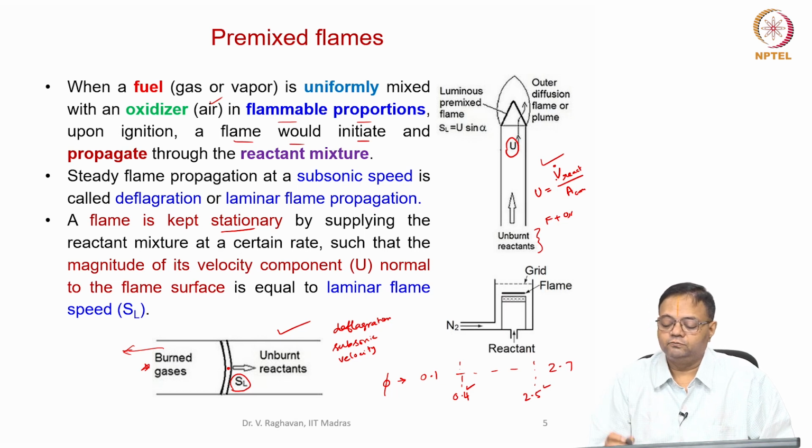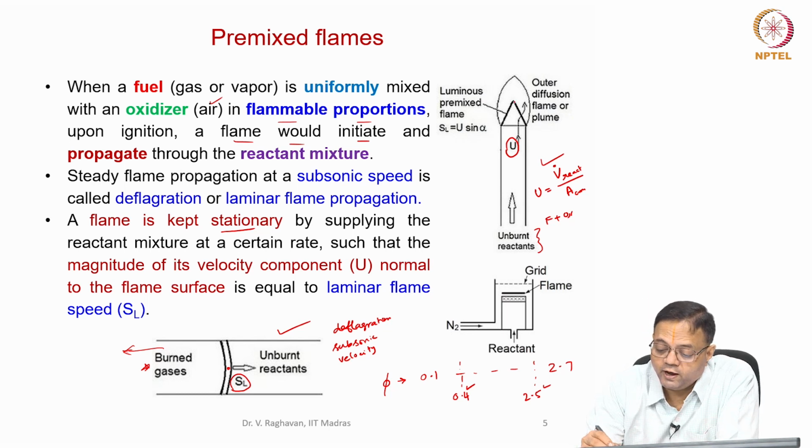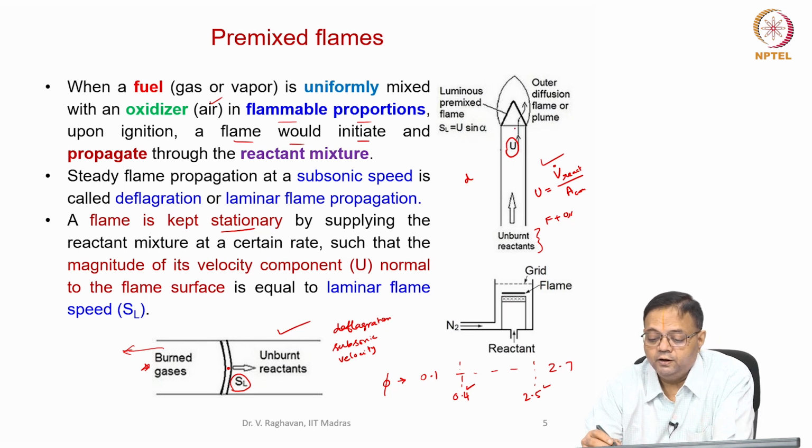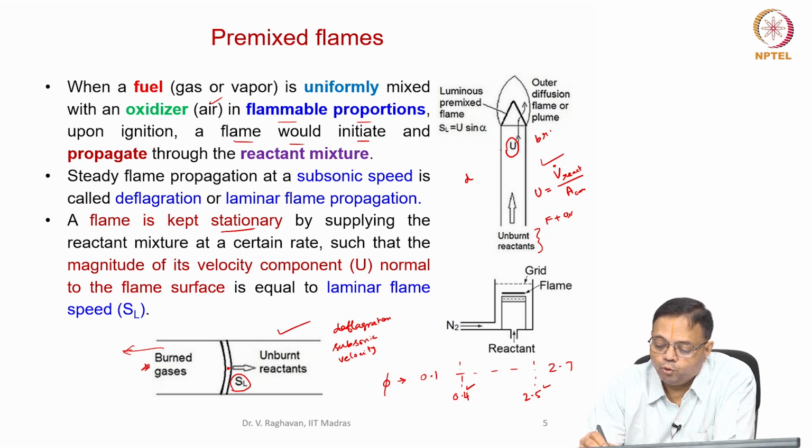So, it is supplied. Now, what happens is a conical flame is formed. This is a cylindrical burner, so diameter D, cylindrical burner. Now, this conical flame is formed at the end of the tube, and this conical flame is bright blue in color. I will show this in the next slide.